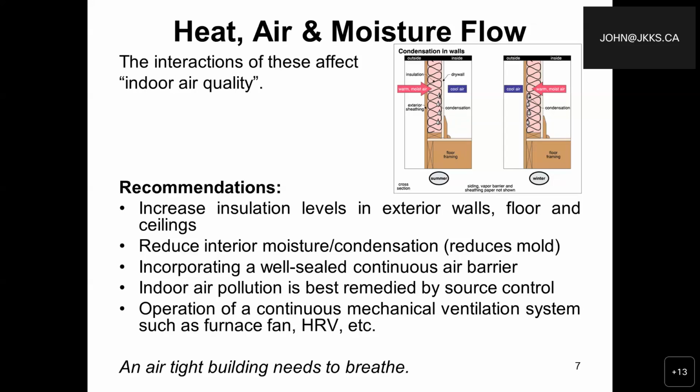In terms of indoor air pollution, we have to think about it as best remedied by simply identifying the source and controlling it at the source. Then there's the operation of continuous mechanical ventilation systems such as a furnace fan, a heat recovery ventilation or energy recovery ventilation system, or simply even something like a bathroom fan. Again, an airtight building needs to breathe. And nowadays with new builds, as I mentioned, the codes require that we build tighter, with less air leakage in a home.